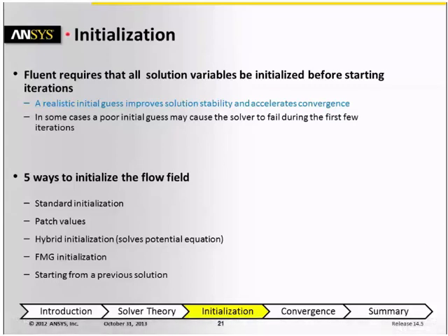Now we're going to move on to the topic of initialization. Because Fluent uses an iterative method to solve the governing equations, all solution variables need to be assigned an initial value, or initialized, before iterations can begin.